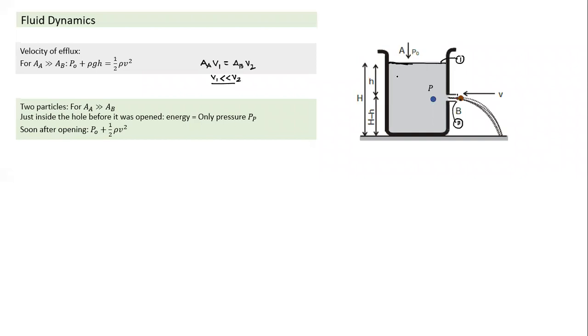So the velocity at which the liquid particles move downwards at the surface will be much lower than the velocity of the liquid particles flowing out. When we calculate kinetic energy, you square it, so this term becomes negligible. In the majority of cases, though the right equation should have both the v1 term and the v2 term, where the vessel is large compared to the size of the opening, we ignore the v1 term. So when we write this equation here, what are the terms we write?